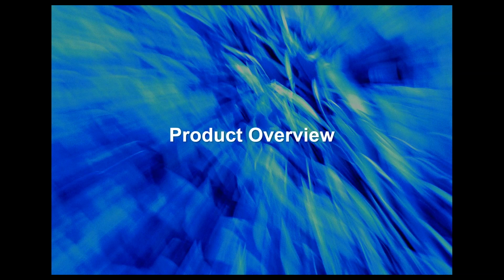Let's say in any geotechnical software, we have a geotechnical investigation team. They provide us with the raw data, and then we take the borehole data and experimental data produced by them and use those data for geometric modeling. The very first step in any finite element software is geometric modeling. In geometric modeling, we use the bedding planes data or borehole data given by the investigation team, and we form the layers and the majority of the site conditions. And then the second step is the material definition.